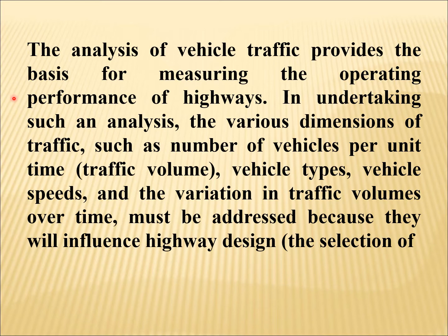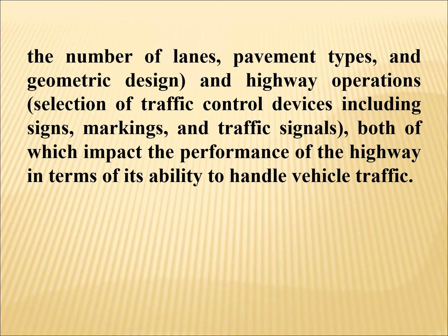In undertaking such an analysis, the various dimensions of traffic, such as number of vehicles per unit time, that is the traffic volume, vehicle types, vehicle speeds, and the variation in traffic volumes over time, must be addressed because they will influence highway design: the selection of the number of lanes, pavement types, and geometric design.